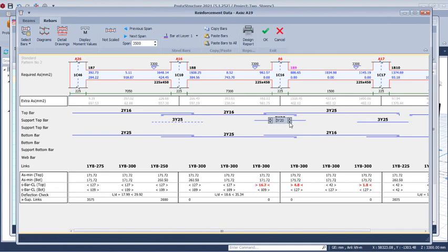Then reduce the reinforcement. Reduce it to 16. Reduce the bar here. Okay, it's failing. You can use 3Y16, but make it a second layer, just like this. Click on this drop down, select second, just like this. You see it failing, increase it to 20, it has passed.